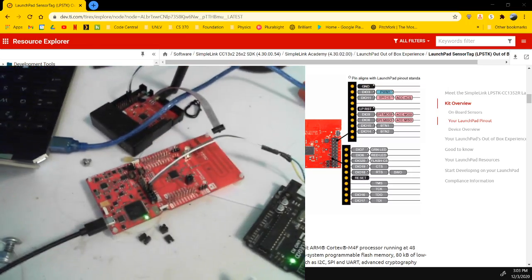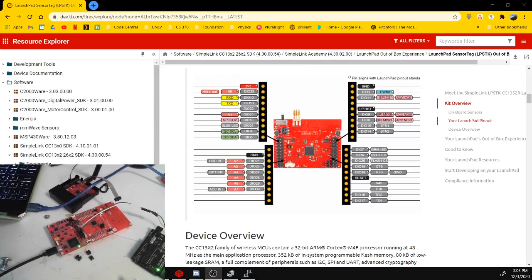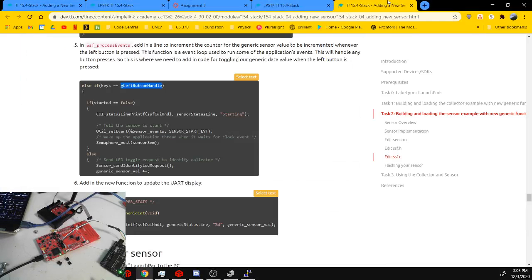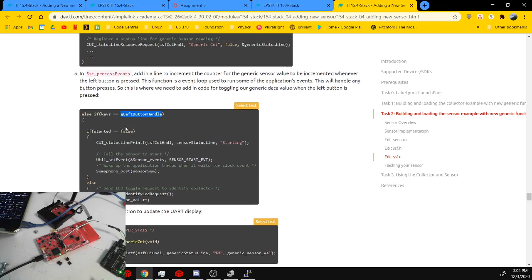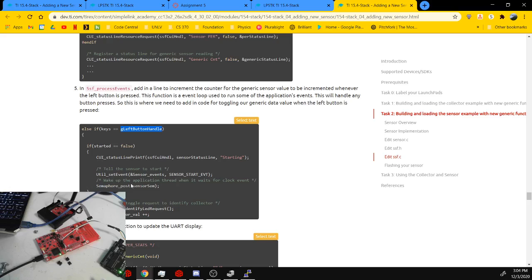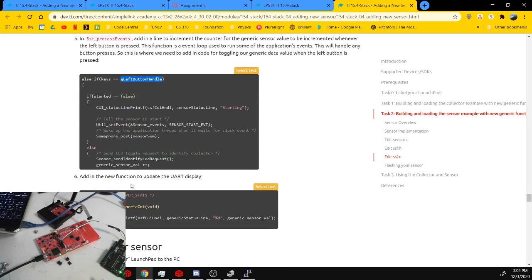Anyways, lower that back down. We can close this, it's fine. So instead of the left button, basically I kept this the same, but I put the right button here, and I put what was on the right button code on the left button, because the right button code, right above this section inside Code Composer Studio, actually disassociates the sensor from the network. So I made the left button disassociate the sensor, and the right button is now doing all of this. So I just swapped them out. And I think that's all the changes I made. Yeah, that's everything to get the button presses working.